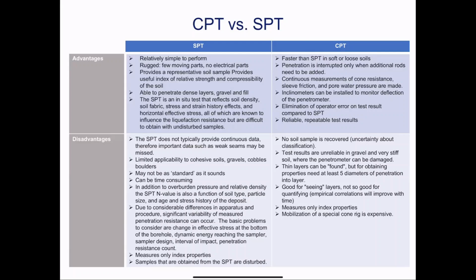SPT is a dynamic compressive method, so it can sometimes penetrate a very dense granular material, whereas CPT only moves at 10 millimeters per second with limited push and stress, so sometimes you will get stuck with a CPT.